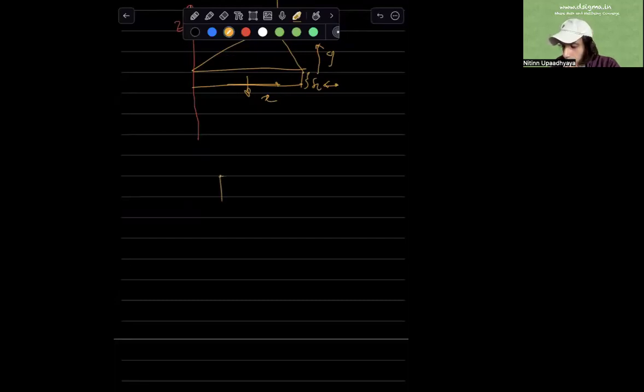Now, if I look at a vertical column in this manner, and I'm just going to exaggerate the drawing, let's say this has a height h, and at the top of this column, which is exposed to the atmosphere, the pressure is P naught. As we go down the depth, and I'll refer you to a video where we talked about how the gradient of pressure aligns with the direction of gravity, perhaps to a depth of z, we consider a tiny infinitesimal rectangular element at this depth. The depth of this tiny rectangular element is dz,